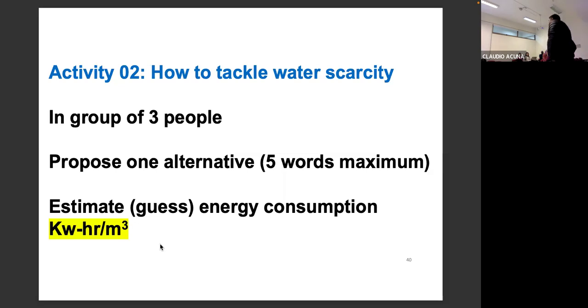So what we should be doing is evaporating. We cannot use reverse osmosis anymore. The limit is 70%. Otherwise you get what's called polarization of the membrane, and then you need to move to forward osmosis. It's a funny name, because it's just osmosis, so they call it forward osmosis. It means you have saline water, we're talking about 70,000 microsiemens per centimeter,